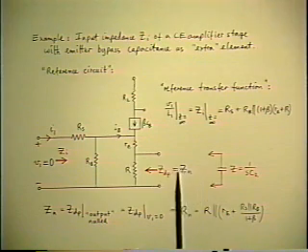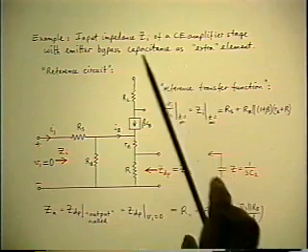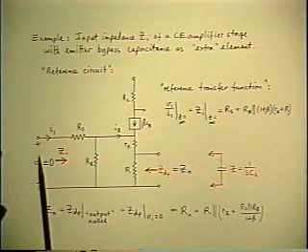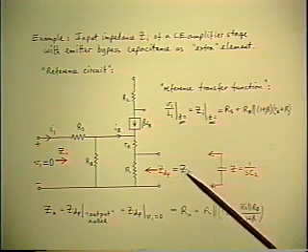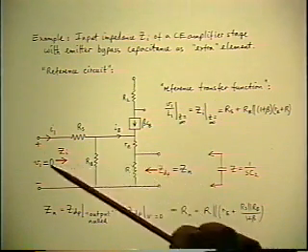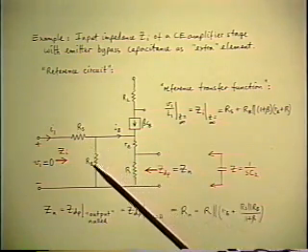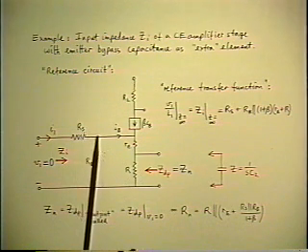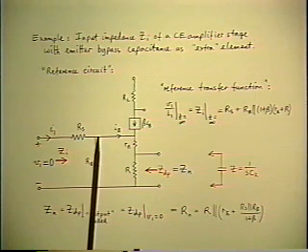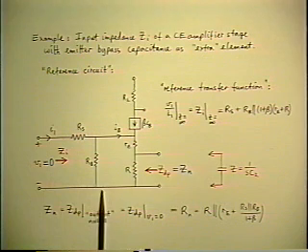Now this is a little tricky, isn't it? Because you've got to remember there's a current source out here, and you're adjusting two sources until the voltage across that current source nulls. But when you're looking in from the second source and asking what is the impedance, it thinks that the RS is back in parallel with the RB, because the voltage at the right-hand end of RS is the same as the voltage at the top of RB, and the voltage at the left of RS is the same as the voltage at the bottom of RB, namely 0.